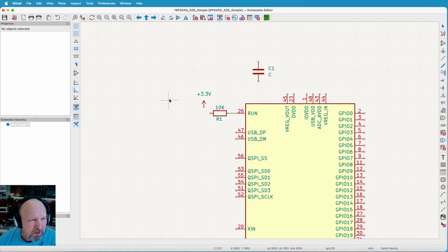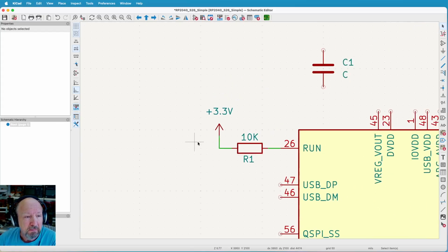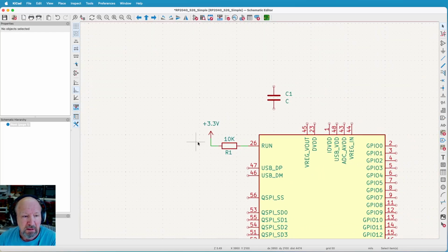And also, as you notice, as I get my cursor really right on these circles, you can see that it goes from that cross to a pencil-like thing. That means it's going to draw a trace. So I don't even have to click anything else. I can just click on the circle and click there. You'll also notice that when I complete a trace that the circles vanish. If they don't vanish, you're not connected. Okay, so there's that. Let me just add a couple more traces.